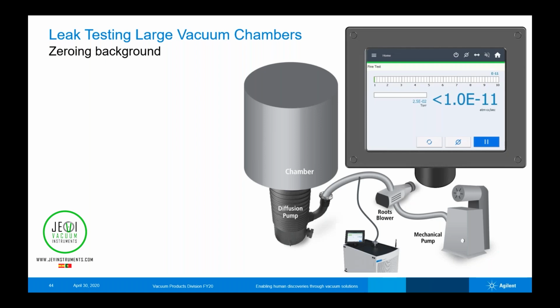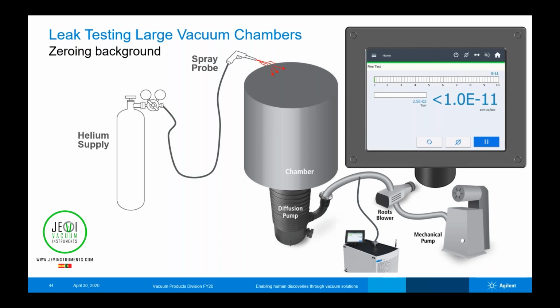and this is what our display looks like on the detector, and we start spraying helium, over time, our helium level is going to increase. And you see now we've come up off our baseline reading of the leak detector. We're indicating we've got a leak in the 10 to the minus 8 range. But the inside of our chamber is becoming polluted with helium. There's a low level of helium in there, and it can take some time to pump that helium away.